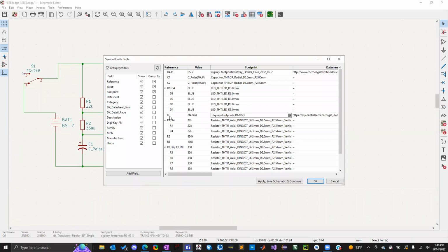There's a standard for the naming scheme for all the components on a circuit board. I can find that website link. I'm not going to try and find it now, but there's a whole list from A through Z of all the different types of components. You can also give them their own names, like the battery is BAT1 instead, which helps the viewer because they'll actually see that name on the board.